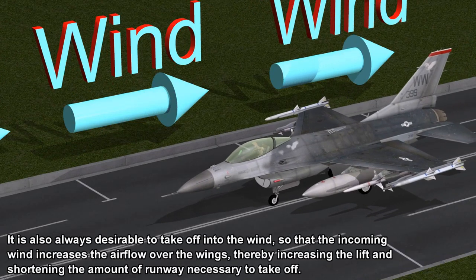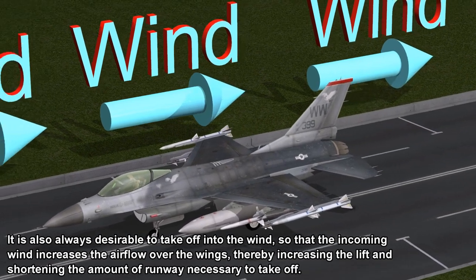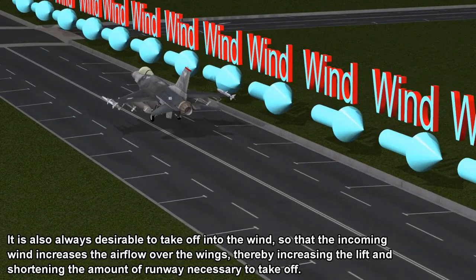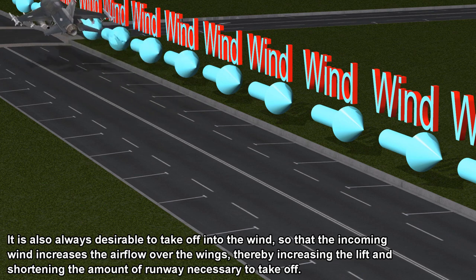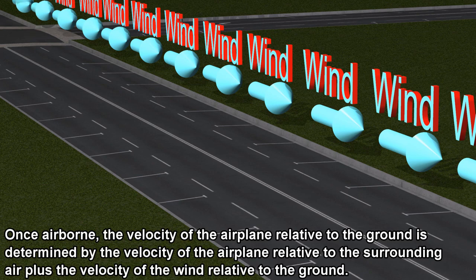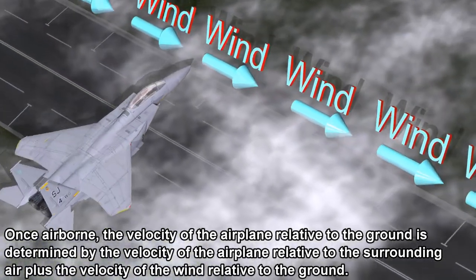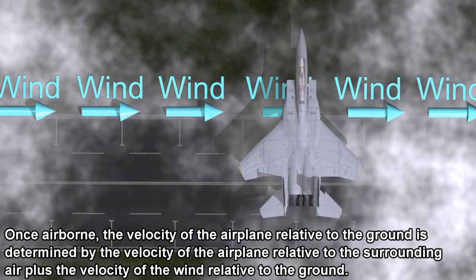It's also always desirable to take off into the wind, so that the incoming wind increases the airflow over the wings, thereby increasing the lift and shortening the amount of runway necessary to take off. Once airborne, the velocity of the airplane relative to the ground is determined by the velocity of the airplane relative to the surrounding air, plus the velocity of the wind relative to the ground.